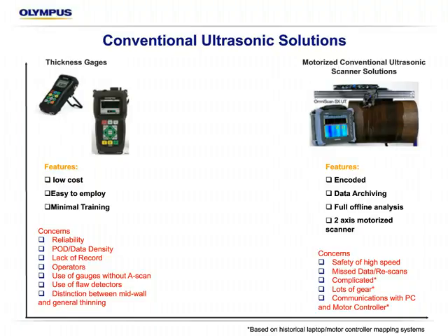Also, the ability to miss data. We'll look at this a little bit further, but the typical sensor used in conventional ultrasonic mapping systems is usually a dual crystal, very small, about 0.187 inch. So imagine moving at very high speeds. Our in-service conditions aren't always the greatest. You have rough walls. You could possibly lose coupling or fall into an actual outside surface rough area or OD corrosion that could cause a data point to actually be missed.